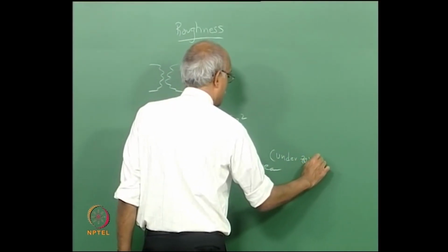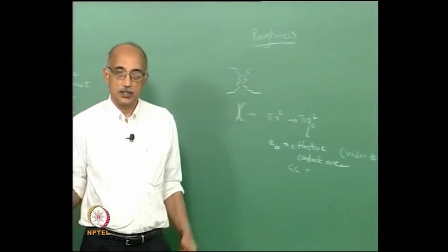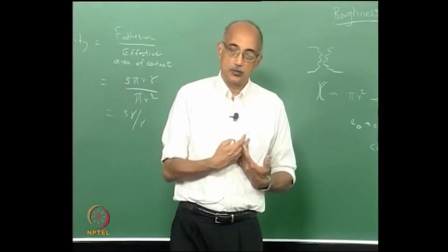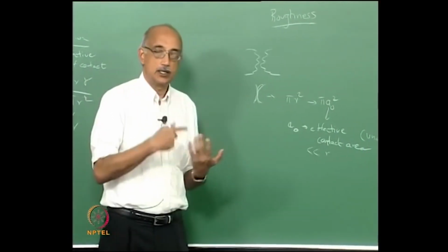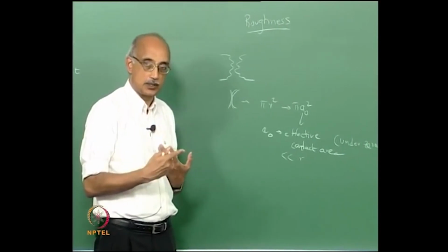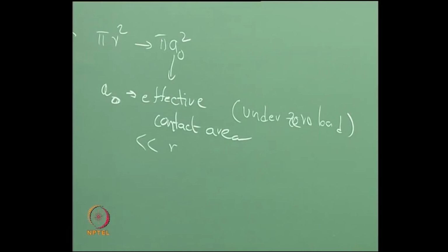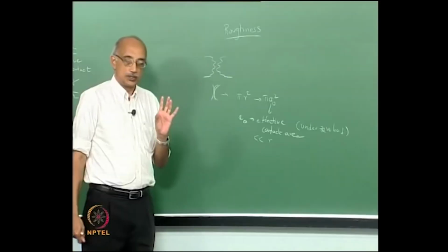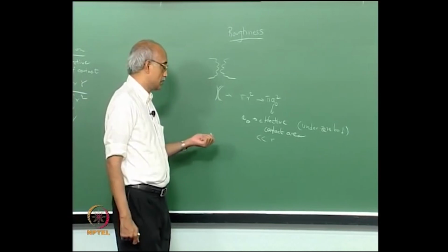So, there is nothing pressing the particles against each other. They are basically in loose contact with the surface roughness providing the effective area of contact between the adjacent particles. And so, because the effective contact area is significantly reduced in the case of a rough particle, the adhesive force between two adjacent particles is also significantly reduced.